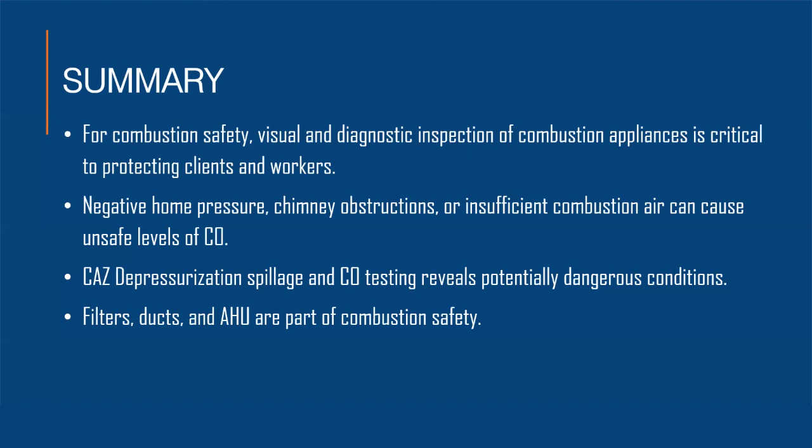Using the combustion appliance zone depressurization testing and checking for spillage can shed light on potentially dangerous conditions that you might have created with your well-intended air sealing work.